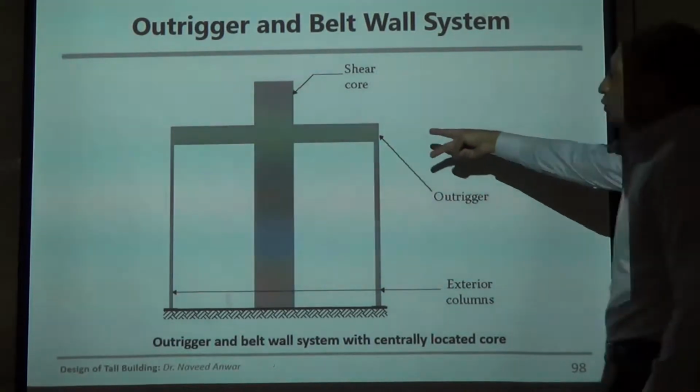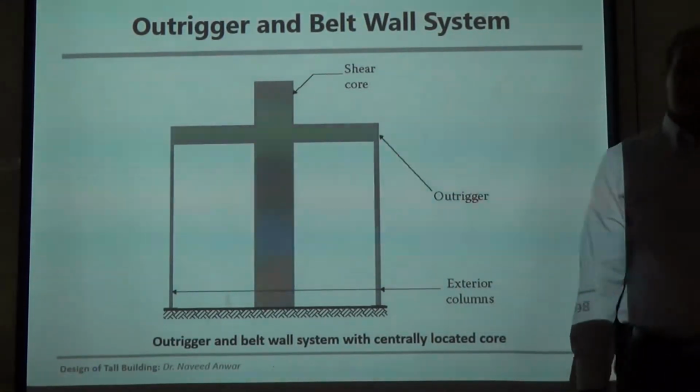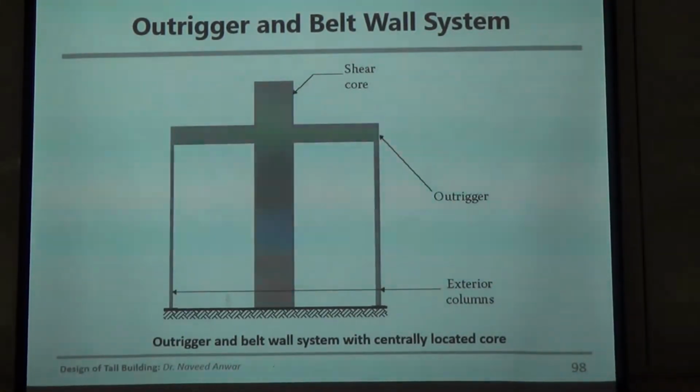As deep as 2 floors, 6 meters, or 3 floors, 9 meters. Big, very huge beams, running two or 3 floors together. These very big beams connect the outermost column, we call them super column, and the core wall, and they are placed in few locations.